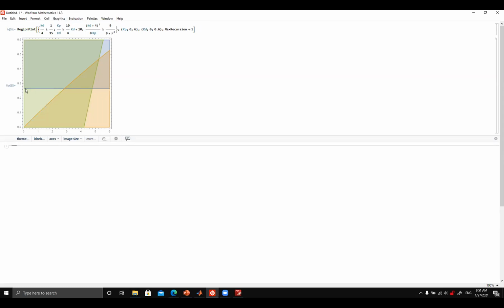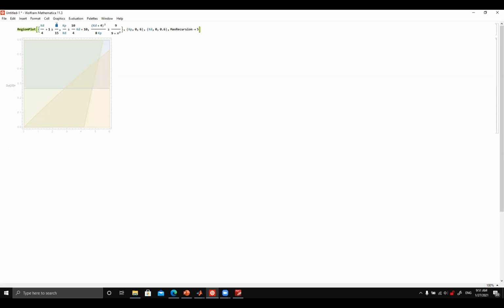So we have three regions here. The region in blue, right? This corresponds to the first expression here, which is the expression on the settling time, which was basically this, right? Then we have the region in yellow in the graph. This corresponds to the fact that we want the zero to lie far enough to the left such that its effect on the second order system is negligible. Then finally, we have the requirement on the percent overshoot, which is the one in green, right? So we see that they all intersect in this region here.